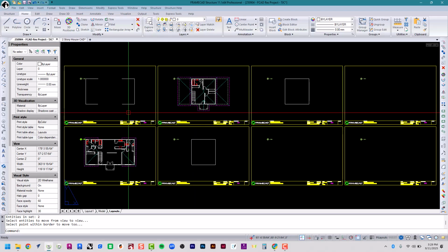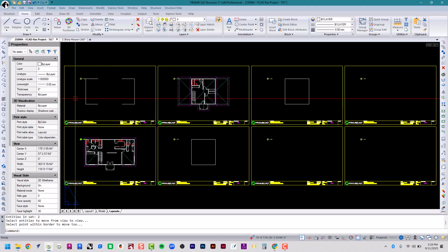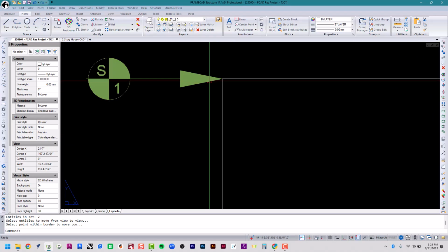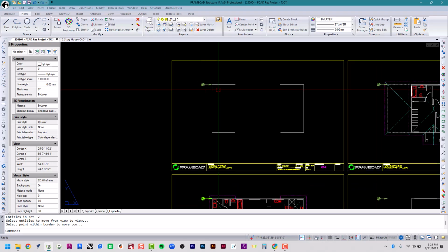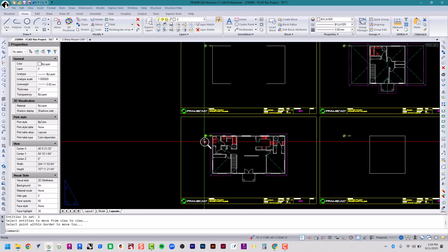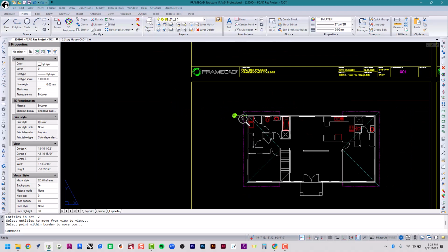Okay, we're going to need these lines later on, so that way we can draw our trusses. Look at where the reference point is. The secondary reference point references this corner. This secondary reference point represents this corner, and the primary reference point represents the same exact corner as well.